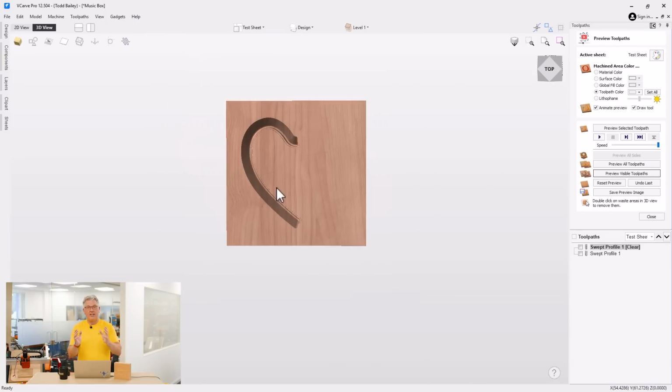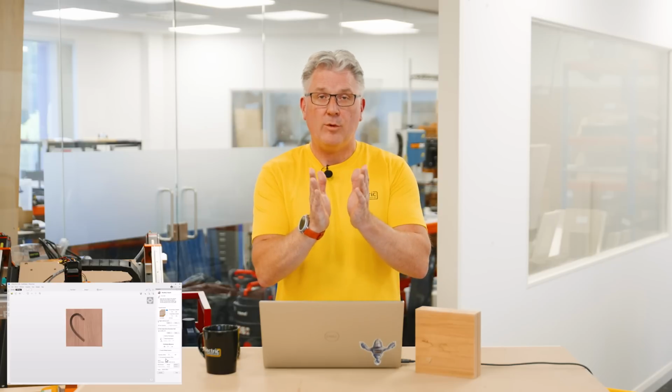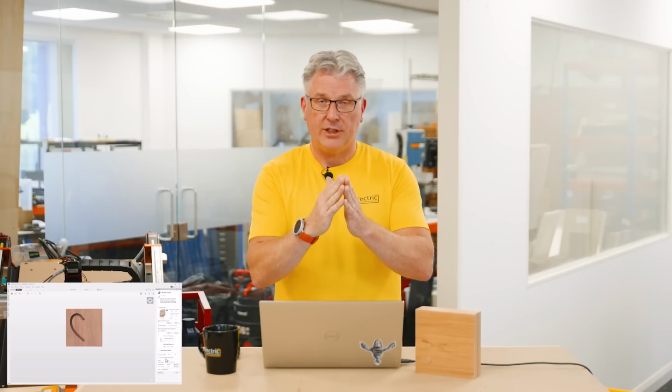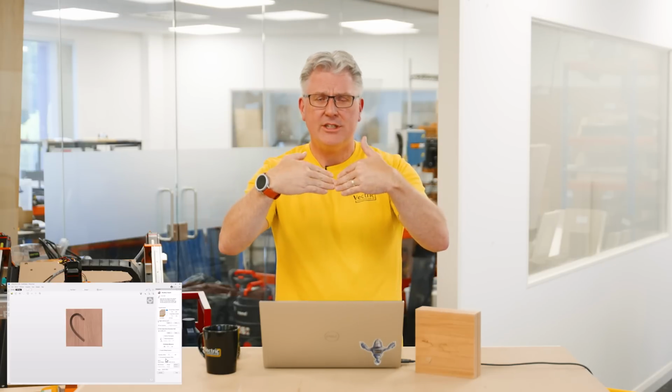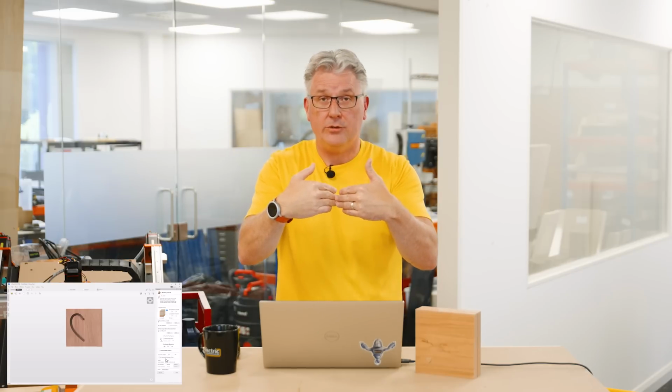So now that I have that kind of sorted out, let's just review this really quick. This area right here with your boundary offset, make sure you choose the right option here that's going to work for you. And remember that we won't allow you to actually cross over each other. So especially if you have an inside really tight turn, we may actually throw up a warning that says we can't actually calculate this toolpath for you.